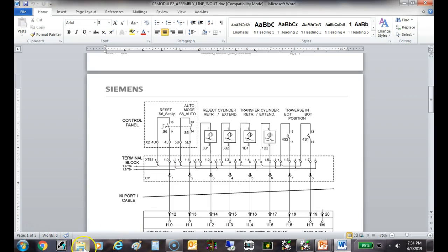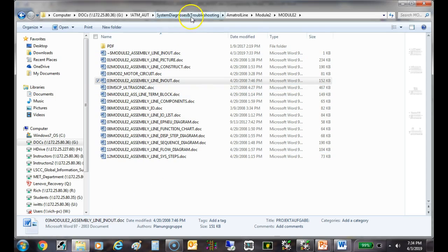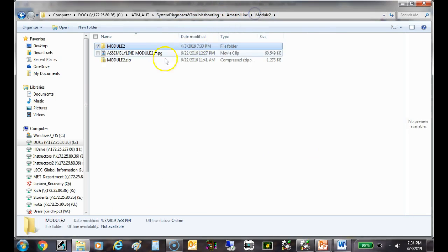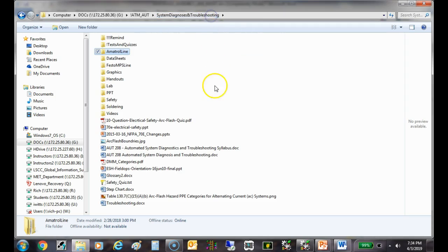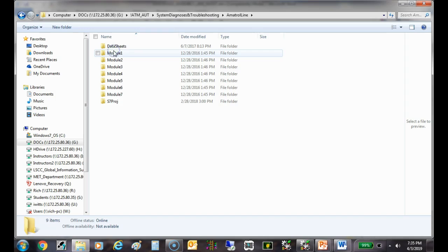I wish I'd have shown you that on the other one. Let me bring up the other one. So the signal wire is going to be blue instead of black, because it's the power lead for the sensor. So the magnetic reed switch is basically not powered up, right? You understand? So its signal wire is actually considered also its power wire. If that makes sense. It does to me, but I'm the teacher.